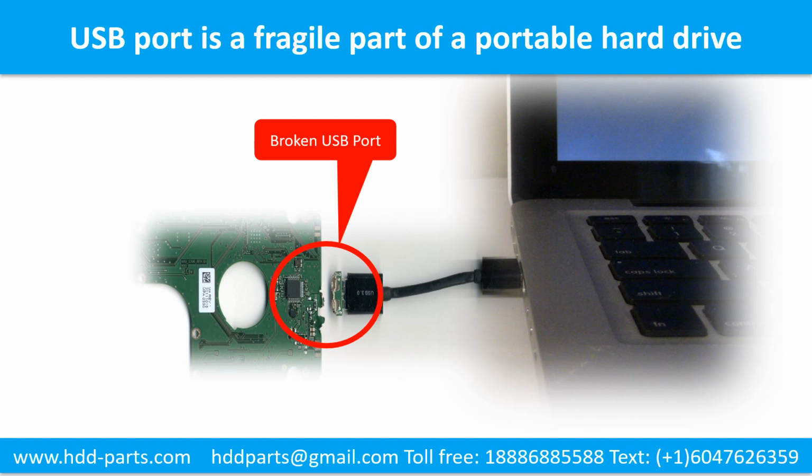And also, every time you use the portable hard drive, you need to plug and unplug it. Sometimes the power connector is broken, but most of the time it's the USB port that is broken, and most likely the broken part is the thin PCB board inside of a portable hard drive.